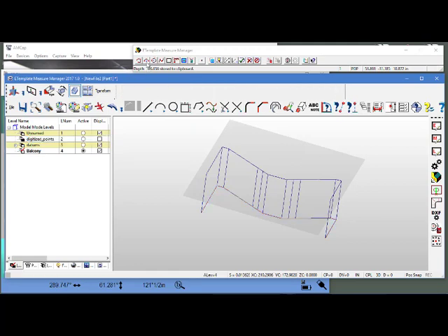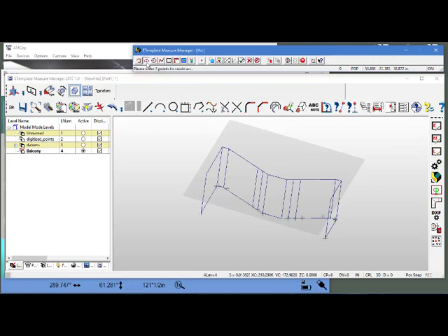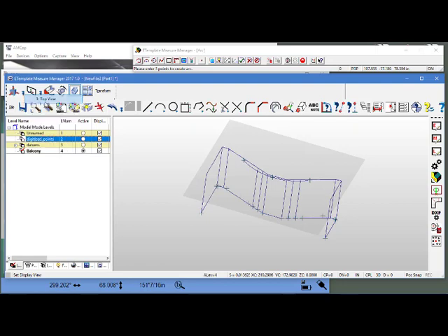There's a couple of ways we can shoot the balcony. The first way I'm going to shoot it is a simple 3-point arc. And it presumes that the arc is constructed very, very well. That's a presumption I don't think you often want to make. But by just doing 3 points, it will create the arc. And if we take a look at this from the top view, you can see here's my arc.